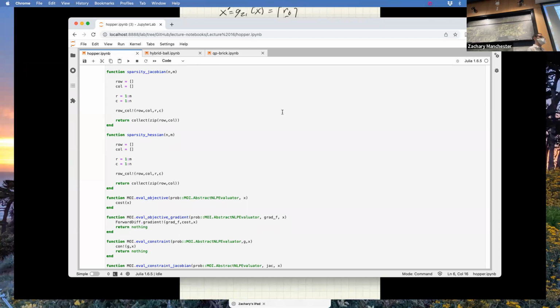They might have a couple of canned gaits in there for flat ground, and sometimes another canned gait for stairs. Anything else, as far as terrain variation, is all just treated as a disturbance. Then you design a pretty robust controller that can handle large disturbances and you're pretty much good to go.